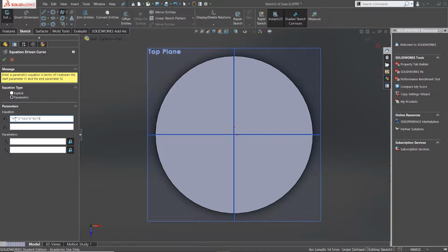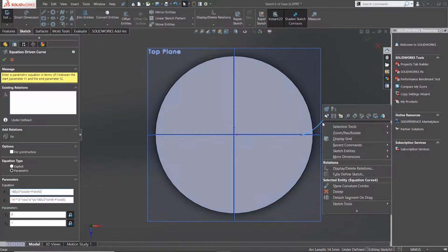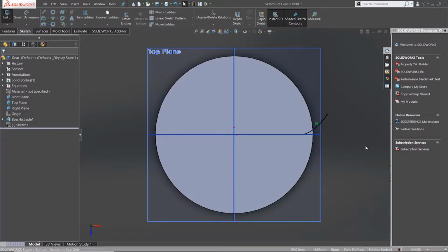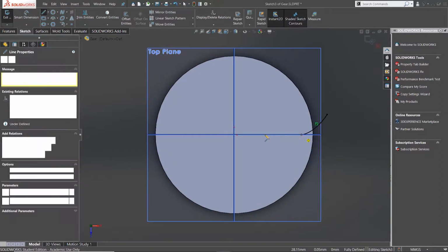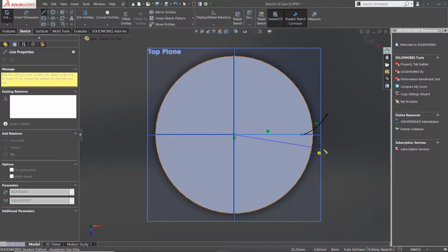The shape is determined by the parametric function of an involute. The first part is the radius of the base circle, which is the starting point of the involute. The maximum is around 0.7, but to be sure, set it to 1. The part of the sketch below the involute doesn't make any sense. So, make it just straight.